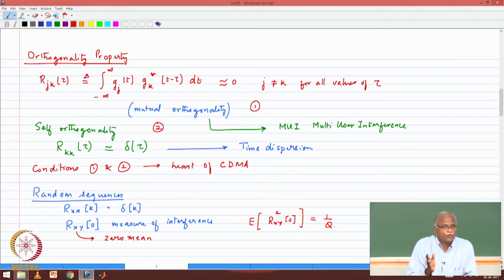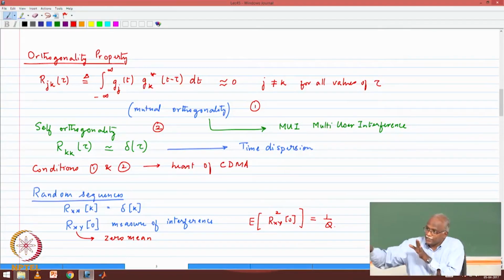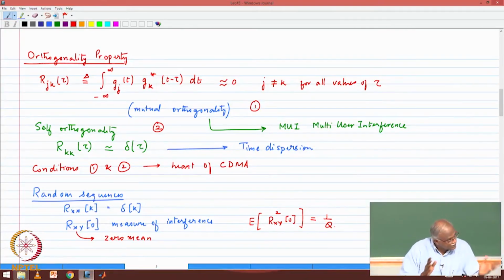So obviously, you don't want your K to become larger than Q, because your protection against interference is primarily dependent on Q. So the way to start to think about the system is that this is a system that is very good at extracting your signal. In the process of extracting your signal, if you have good correlation properties, it will suppress the unwanted signals. It can suppress any number, multiple unwanted signals at the same time. The single operation will suppress them by a factor of 1 over Q, and that is what makes the system robust.